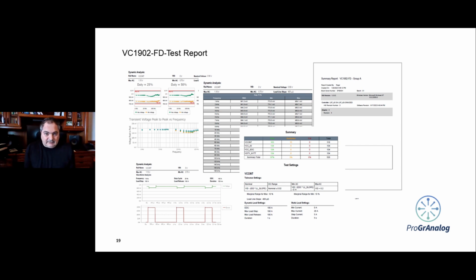How can you do corner testing without putting your system through the corners? We've spent quite a bit of time developing an API which works in conjunction with our GUI, so you can plug in all your favorite bits of bench equipment, which is going to be necessary because the amount of testing is large, to feel confident about getting a high current device out into the market with the optimized PDN, and feeling confident about the integrity, the data, the power integrity, and consequently the data integrity of the solution.